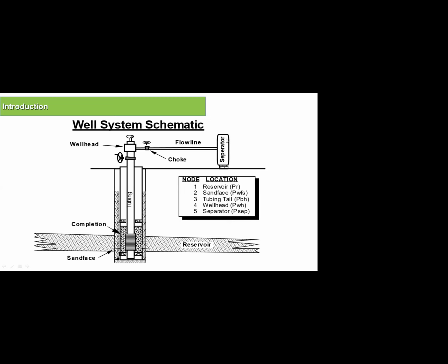Usually we have pressure, normally like 70 psi, 100 psi, and the fluid moving through this flow line defines our wellhead pressure in order for the fluid to move in this direction. And if we have a fluid that's moving through the tubing, it has certain pressure losses, which give us a certain BHFP here and a certain reservoir pressure here. So we will see in detail what nodal analysis is about.